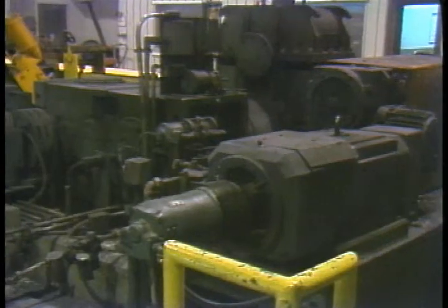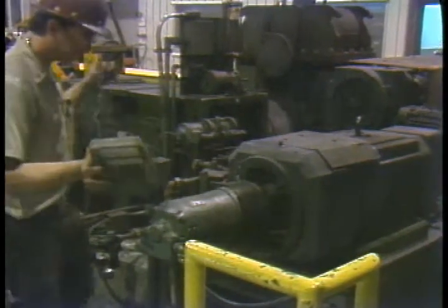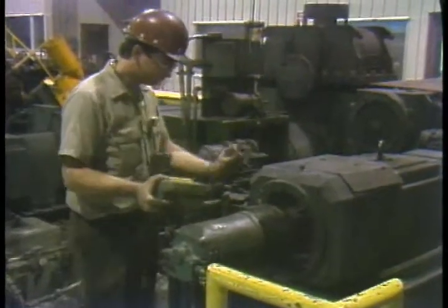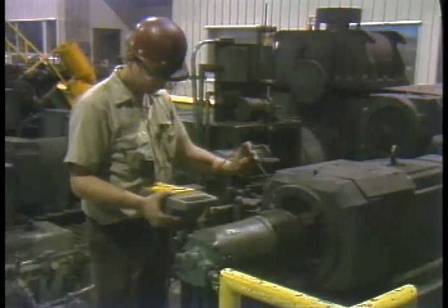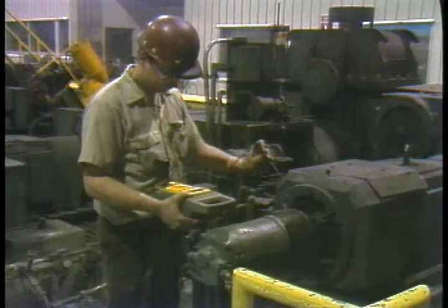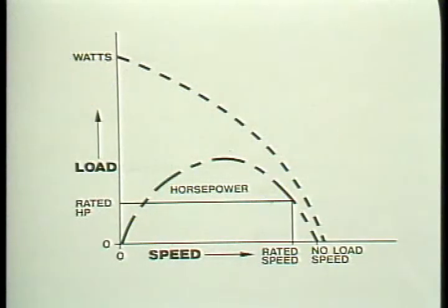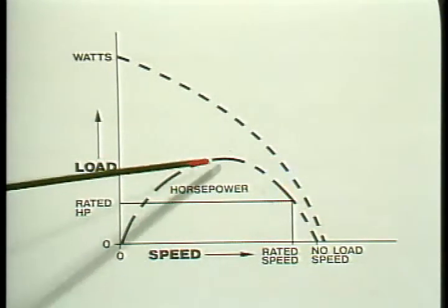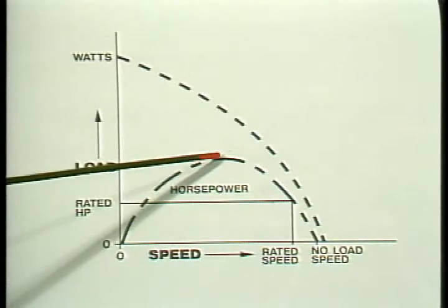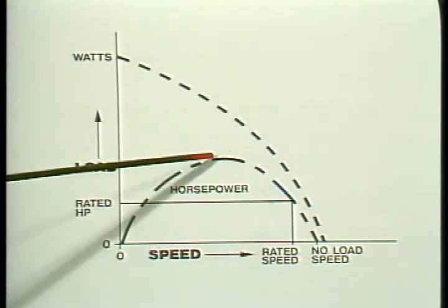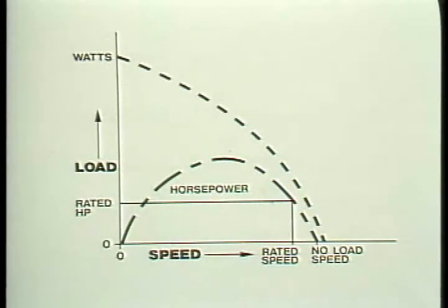Of course, anyone who works around motors knows that they get hot. They will heat up fastest at stall speed when they are consuming a lot of watts, and all those watts are converted to heat. Operating under heavy loads at low speed is almost as bad. At maximum power, the efficiency is high, but the difference between watts in and horsepower out is still large, and a motor will heat up if it is operated under these conditions for very long.